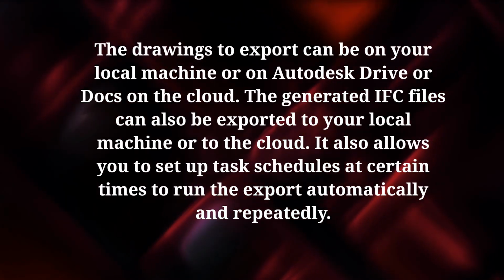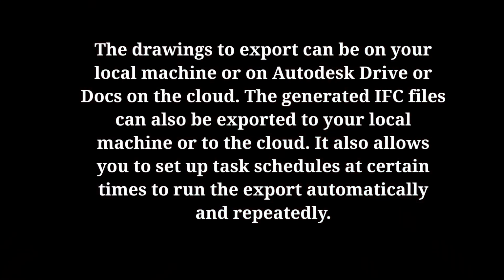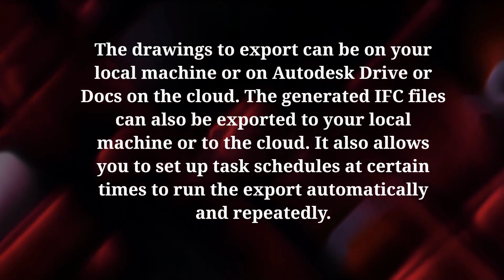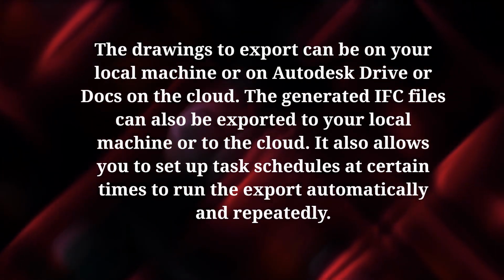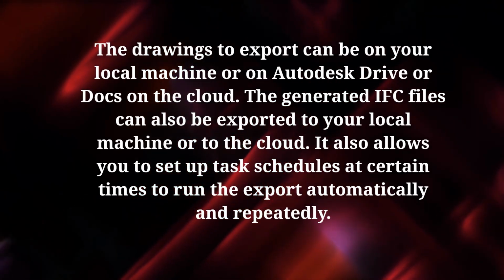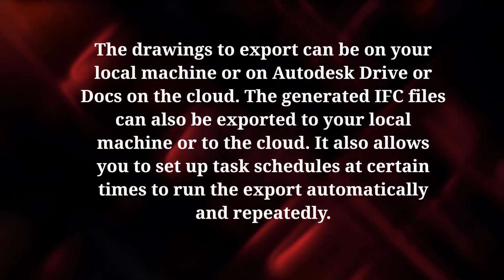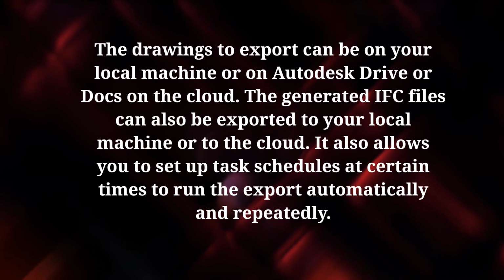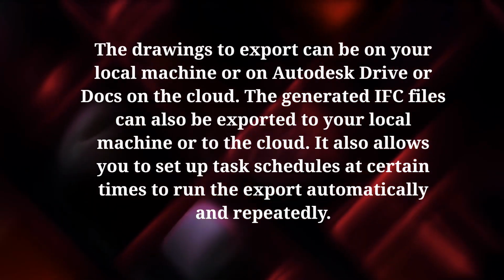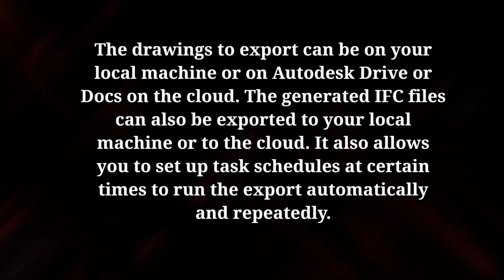The drawings to export can be on your local machine or on Autodesk Drive or Docs on the cloud. The generated IFC files can also be exported to your local machine or to the cloud. It also allows you to set up task schedules at certain times to run the export automatically and repeatedly.